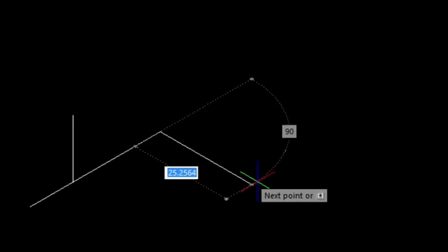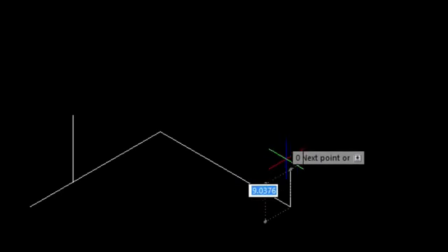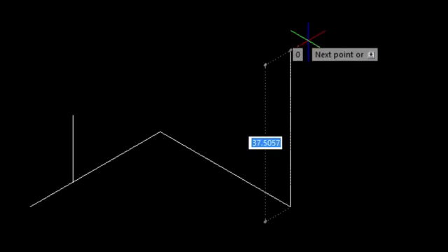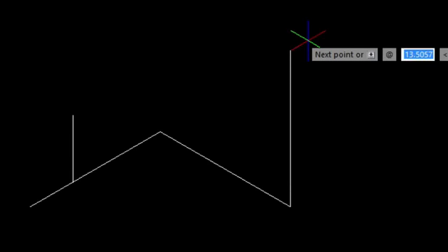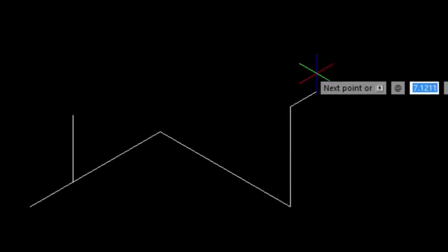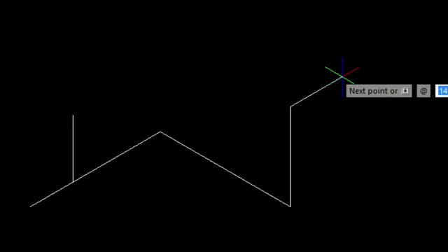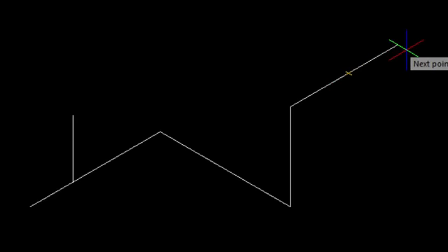So, here I'm creating a sketch by simply using the line command and then using direct distance input, as I'm showing you here. If you're wondering what direct distance is, it's really just like it sounds. For example here, I'm entering the beginning point on a line. Then I'm pointing the cursor the way I need to go, and lastly, typing in 2 feet. With ortho turned on, I can also do the same sort of input in the Z direction. In just a minute, I'll be snapping over these lines and creating my pipe spool.